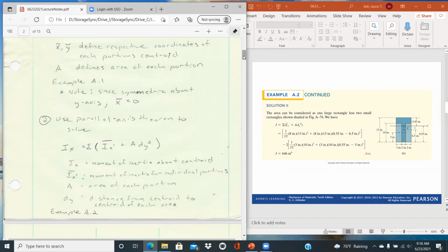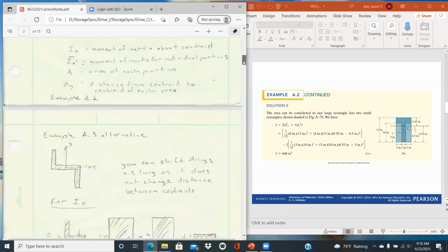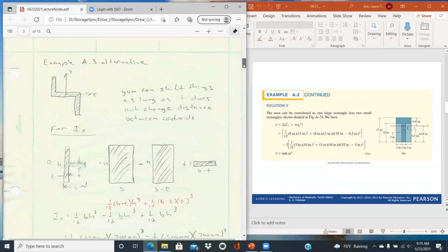For a circular section, pi d to the fourth over 64. So those things are committed to memory because you're generally dealing with common cross sections like a rectangular or circular tube when you're designing things. So those things are easy to commit to memory, but then these things not so much. So you need to know where to look to find that if you can't remember it off the top of your head.